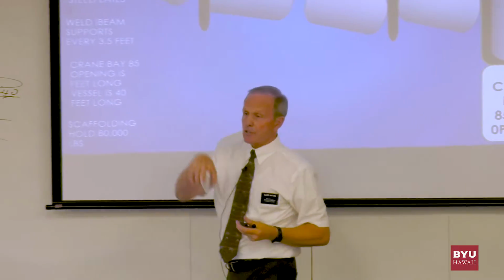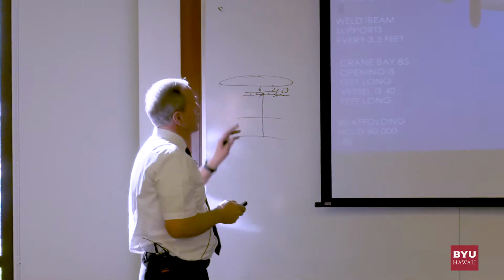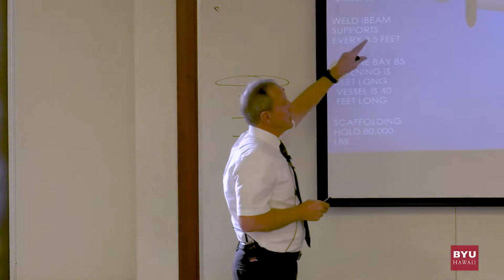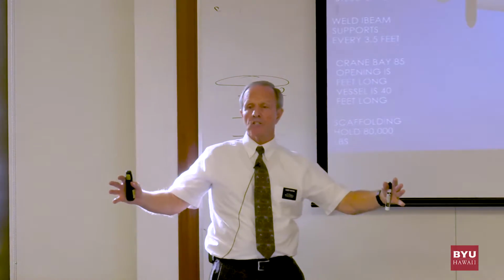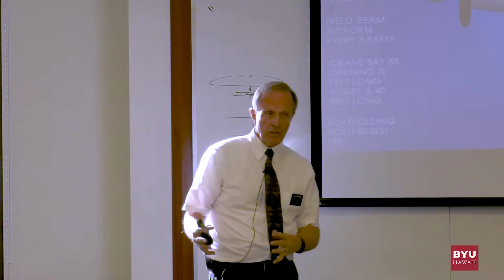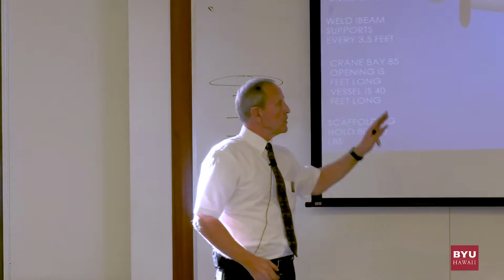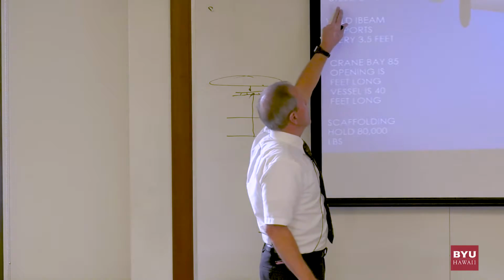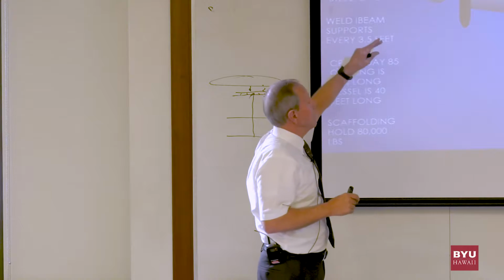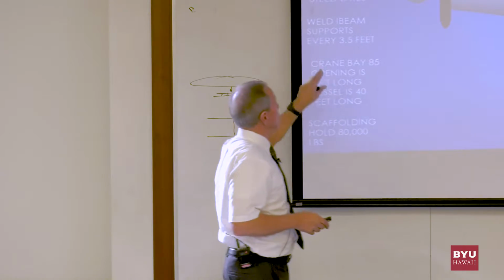That's what we call a pick, is just lifting it. So anyway, this is what happened. We actually built just 4x8 steel plates. We had to put those big plates down. We had to reinforce the entire floor because if that vessel comes across there, it'd go down. So we made half inch thick, 4 foot by 8 foot plates, and all of those were under here so we could start moving that.